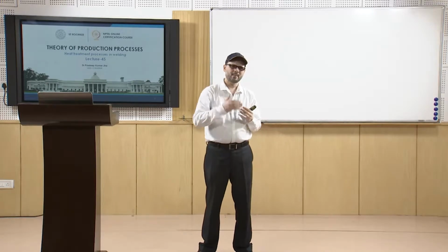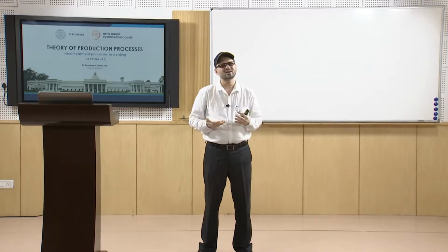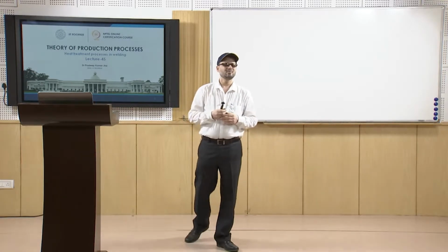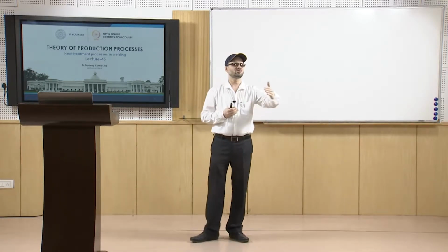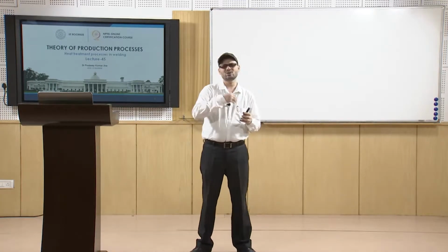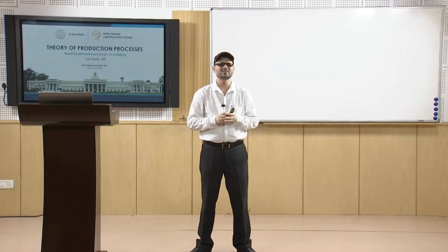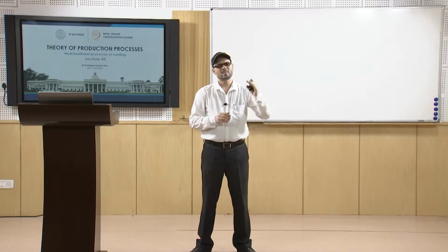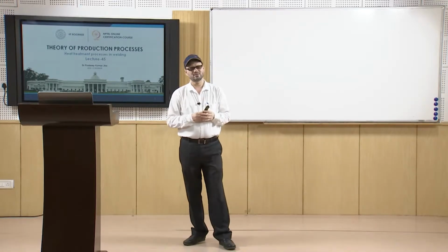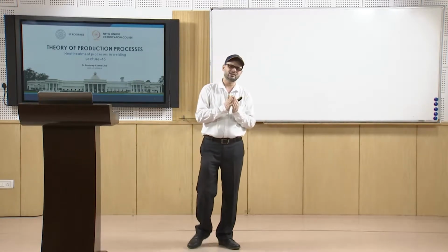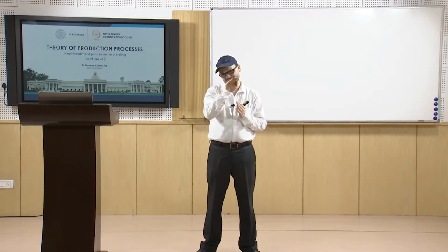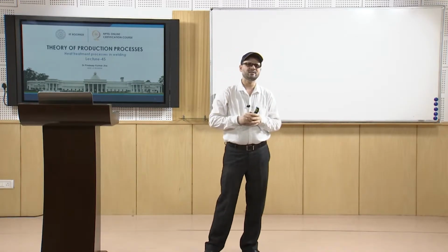Now, heating is up to what temperature and at what rate. That is also important, but we do not go much into detail, because if the heating rate is too rapid, it may have some undesirable effect, but otherwise we heat to a certain temperature, and then holding at that temperature is important.